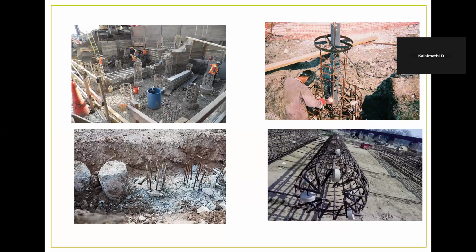And then sheet piles. Sheet piles are the sections of sheet materials with interlocking edges which are driven into the ground to provide earth retention and excavation support. Sheet piles are most commonly made of steel but can also be formed of timber or reinforced concrete. Sheet piles are most commonly used for retaining walls, land reclamation, underground structures such as car parks, and basements in marine locations for riverbank protection.